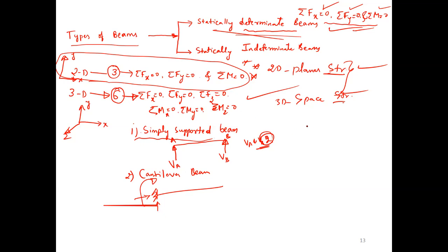Now I will move on to another example. Someone told fixed beam. Now tell me, what is the total reaction in a fixed beam? 6. What are the available equations? 3. Hence it is determinate or indeterminate? Indeterminate. Indeterminate of order what?